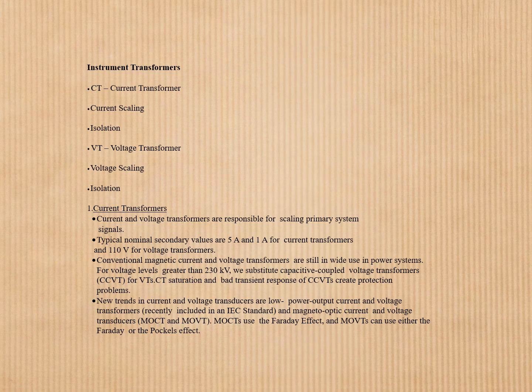New trends in current and voltage transformers are low power output current and voltage transformers, recently included in the IEC standard, and magneto-optic current and voltage transformers, MOCT and MOVT. MOCTs use the Faraday effect, and MOVTs can use either the Faraday or Pockels effect.